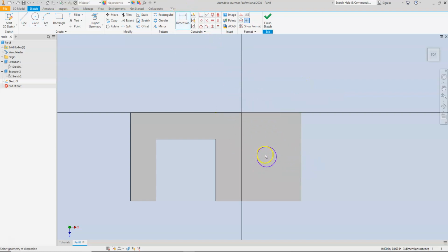Now I'm going to come back with my dimensions, and I'm going to specify where I want this to be located. So pulling that dimension out at 1.25, and then going from side to side. This is 0.75. Locate that. Three things that you always need when dimensioning a hole is the length, the vertical and horizontal axis, and also the size. So three things should always be given when you're locating or putting a hole on a part. So give those three items.